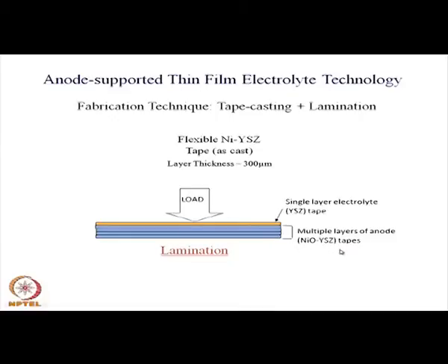In fact, one other thing needs to be mentioned here. To start with, these compositions are basically nickel oxide and YSZ. So, we form the nickel oxide YSZ, and then during its use, when hydrogen is allowed to come in contact with this at a high temperature, the nickel oxide gets reduced to nickel. So, finally, the stable form is nickel YSZ cermet. By taking a few tapes, you can control the thickness, since you need about 1.1 to 1.5.